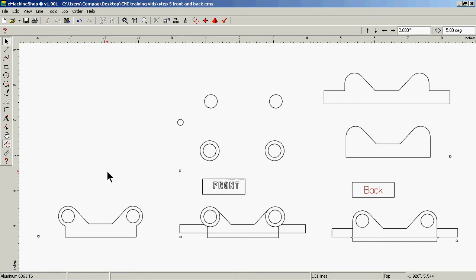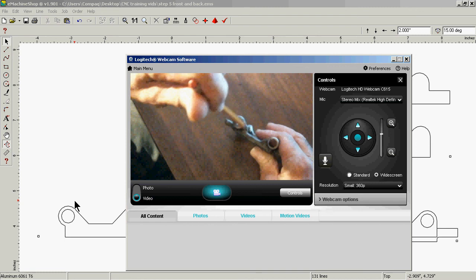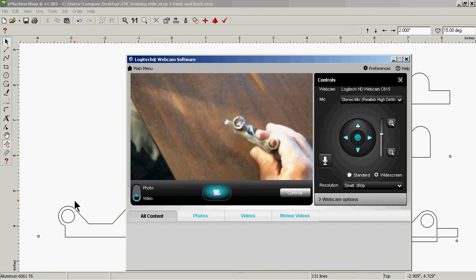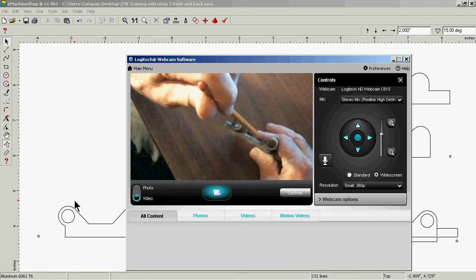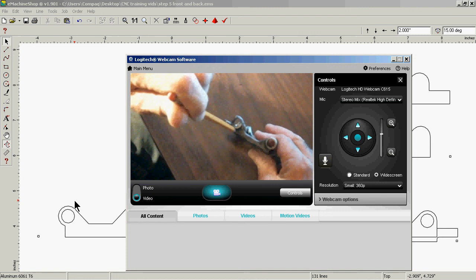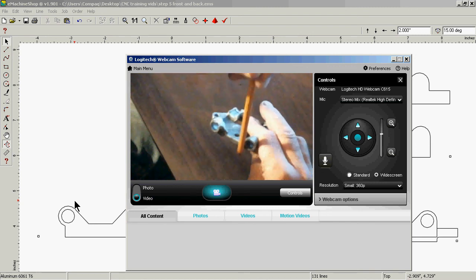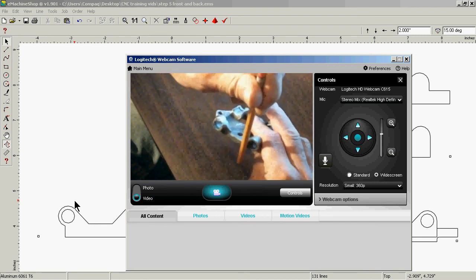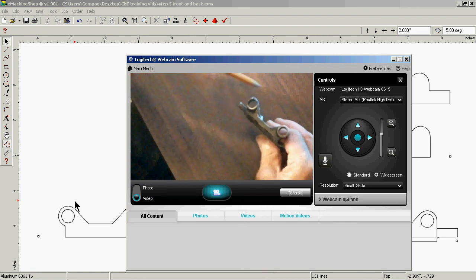Let me go back to the actual video, let you see this. So the first thing we're going to come in and do, first, it doesn't matter. We can do the deep one first, go all the way around. All right. Then we have to come in and just cut this deep all the way around each circle. If we don't, we're going to leave a piece of material sitting right here where coming in from the top cut did not take it out of there. So there would be material. So we have to go all the way around this. That'll clean it up, and then all the way around it to depth.